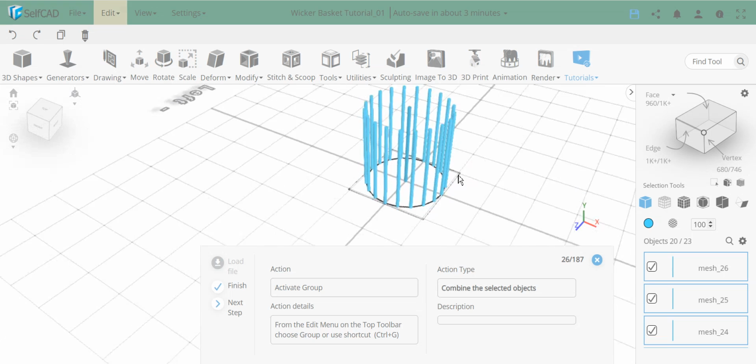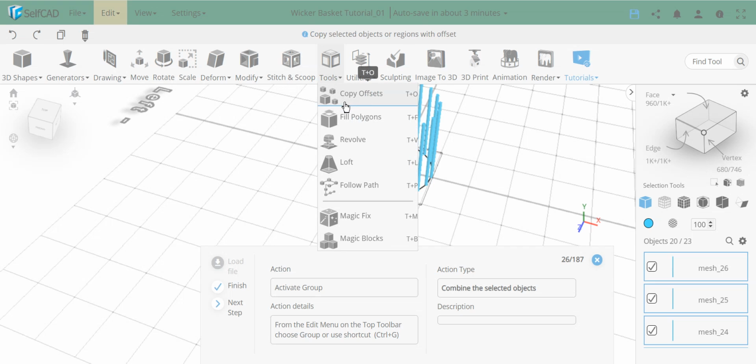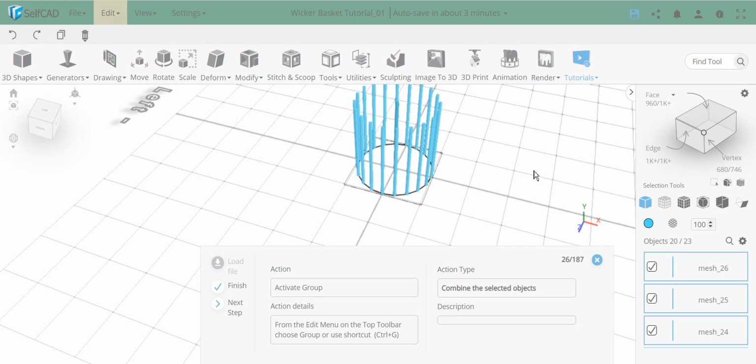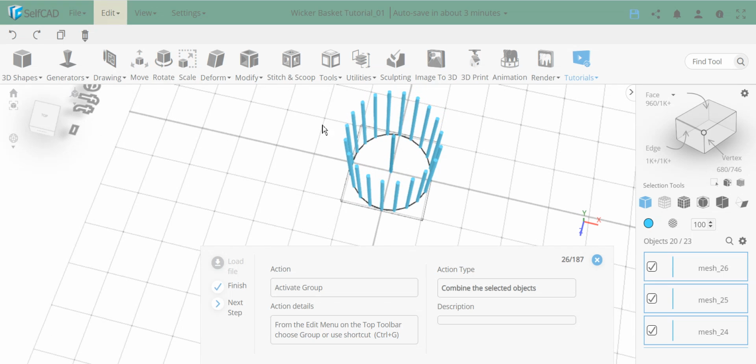There's also another interesting thing: this designer used an approach on a circle to use the Follow Path. There's actually another way. There's no good or bad way, I mean, you could have just used another way. In the Copy Offset tool, a tool we use later, there's a function called Pivot, and Pivot makes a circular copy, which you could have used because it's centered. You could have just made this and pivoted that.